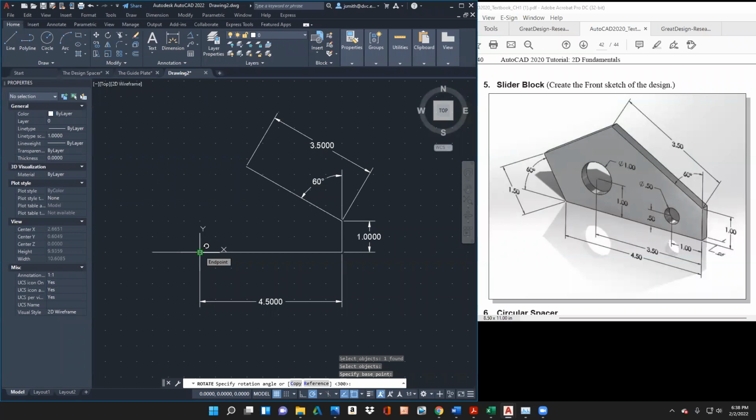So that's, did I do this right? Now I'm all confused. 60 degrees. All right, minus 60 degrees, silly. Rotate, select the object, and 0, 0, type in minus 60. So clockwise is minus. Don't ask me why. Somebody might know. Okay, so now all I need to do is close this up. So I'll just close that up because it doesn't give us that dimension anyway. And so now I'll just dimension this.